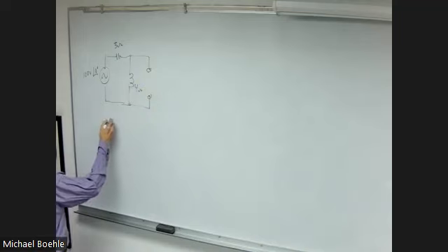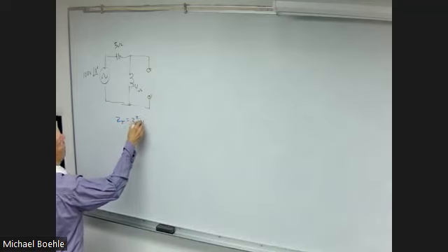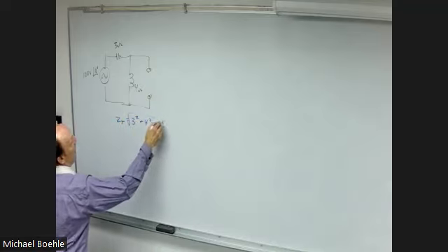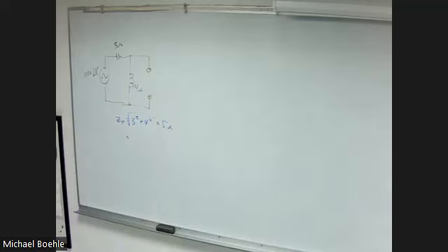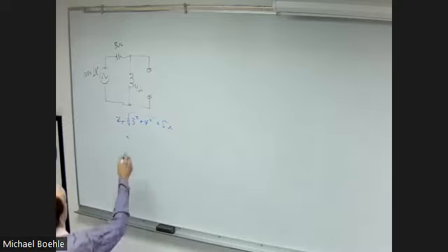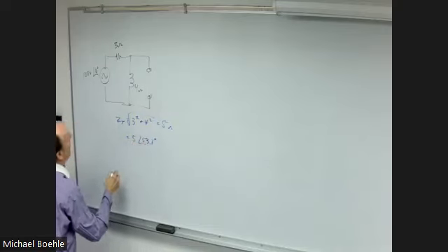Because the total impedance then will basically be the square root of 3 squared plus 4 squared, which is 5. The angle will be the inverse tangent of 4 divided by 3, inverse tangent 53.1 degrees. So 5 at 53.1 degrees. So this is a voltage divider.